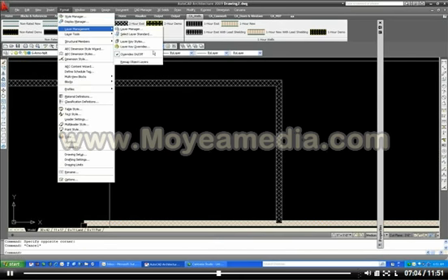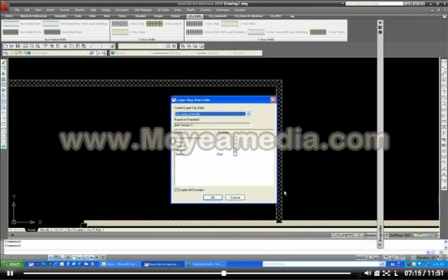So now you can go over here and say I need to draw some demo walls that are being taken out. Go back into the format and the layer management and pick the layer key overrides again, and just change here where it says existing to demo now. So now you got the status changed in the overrides to demo.